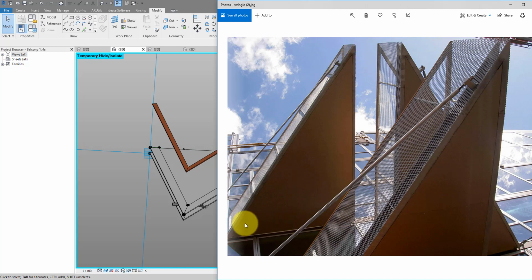If you consider this the left side of the balcony and this is the right side, this sharp point here, if it's more towards the right side, then the balcony will have a left cable. However, if the balcony is leaning to the left side, like this one does there, the cable will be placed on the right side. Otherwise, this cable can clash with the balcony railing, and that's not nice. That's why I have to do 2, and then we can choose when to turn them on or off, depending on the situation of each balcony.